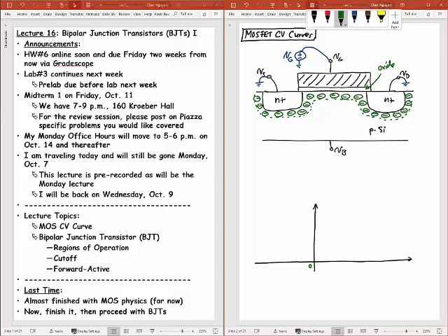let me do this in another color here. I guess I'll do that in red because it's most visible here. But I'll have a series combination of capacitors at first. I have first this capacitor here, which is the oxide capacitor. Then I've got this capacitance, which is the depletion region capacitance. So right here I can call this Cox. We've kind of talked about that capacitance. But this capacitance here, I can call C depletion. Okay? And so that C depletion and that Cox, I could sort of plot on this CV curve here.